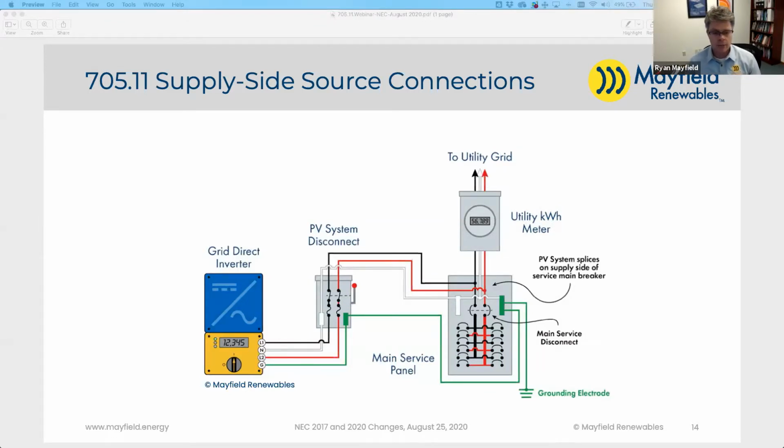The big trick is what's really going to be the temperature on that breaker, July 21st in Palmdale, California, after the inverter's been running for 4 hours. That's the super tricky part. Yeah, the actual specific site conditions. It's a combination of modeling the solar and modeling the breaker in combination with that.